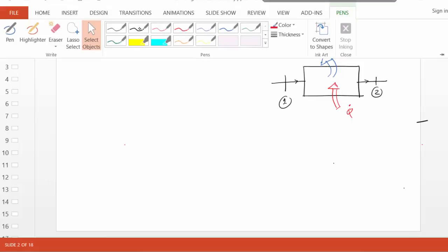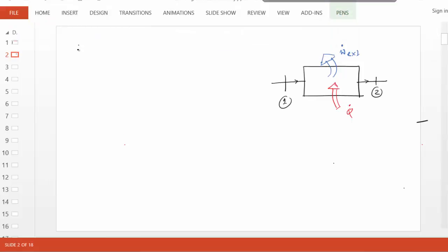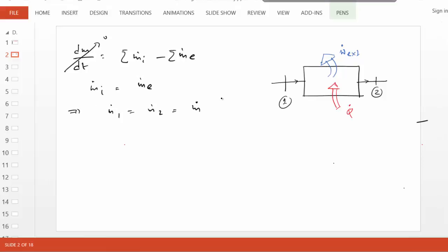If we use the mass, energy, and entropy equation, let me just do one more time. We have already derived this equation. This is the most generic equation for mass. Steady state means this goes out, and there's a single flow. Therefore, m dot i must equal m dot e, or m dot 1 in this case equals m dot 2, and we'll call that just m dot. So many kg per second of flow is passing through the system. Very easy. How about the energy equation?